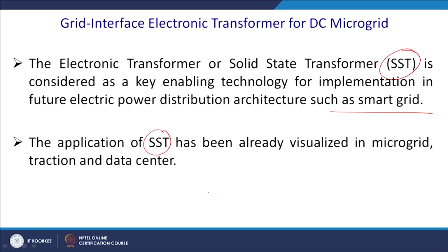So, it is a direct AC to AC conversion, and in between it may have a fixed DC link in case of the indirect matrix converter, so that you can inject the real power and take out the DC power there, and generally this is the mode that has been preferred in our microgrid.